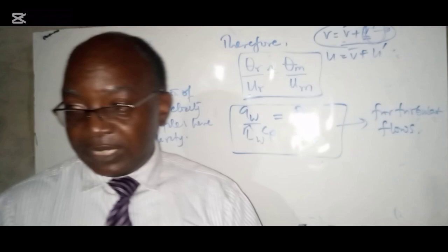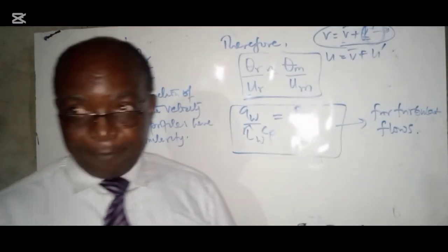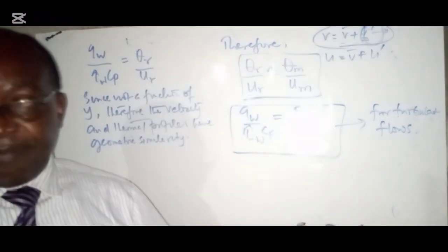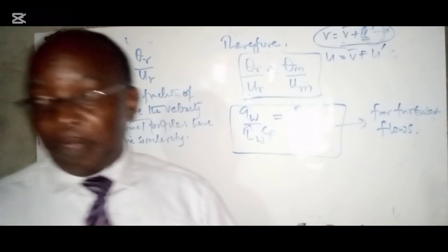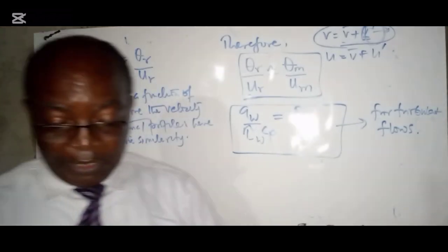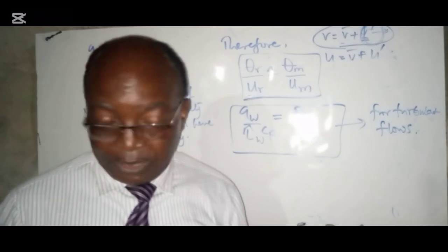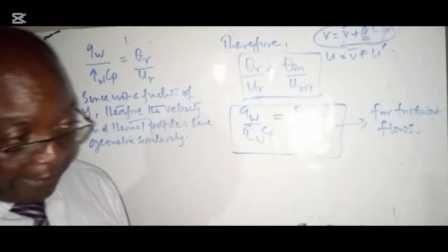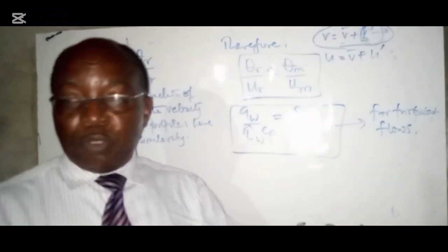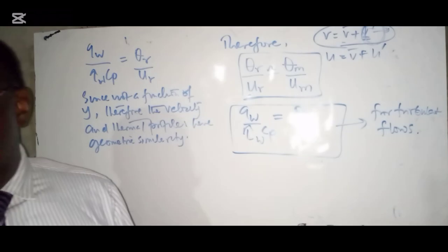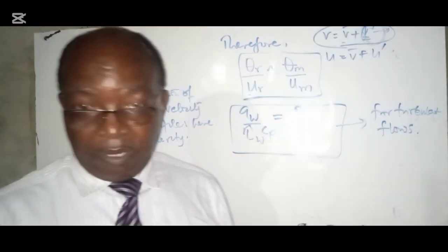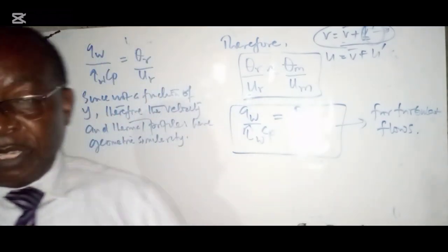And now we have seen the assumptions modified for tubes, because you don't have a free stream, so our Y will correspond to R, which is related to the tube axis. So we are able to get a Reynolds analogy expression for use in flowing tubes.